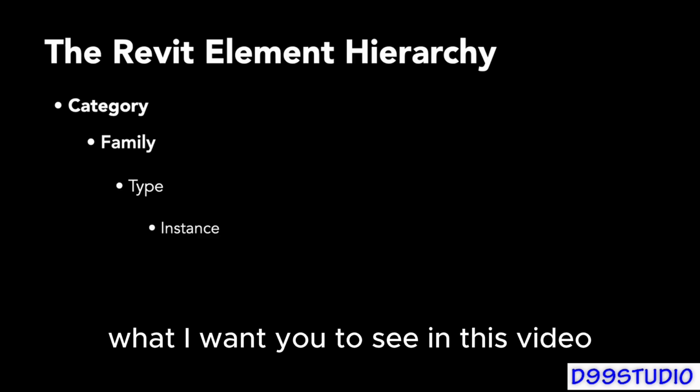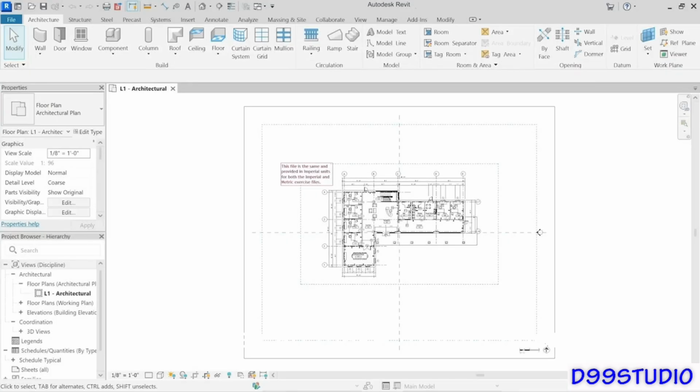What I want you to see in this video is that we can make modifications at each level of that hierarchy, and the impact will be sometimes very localized if it's an instance property versus very global as you move up the hierarchy to things like families and categories. And I'm going to start by showing you how to identify all that information in the first place.